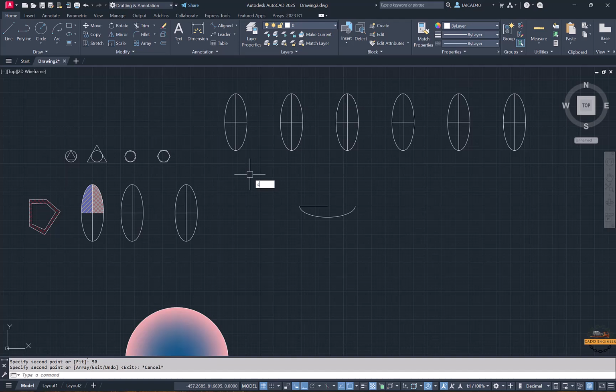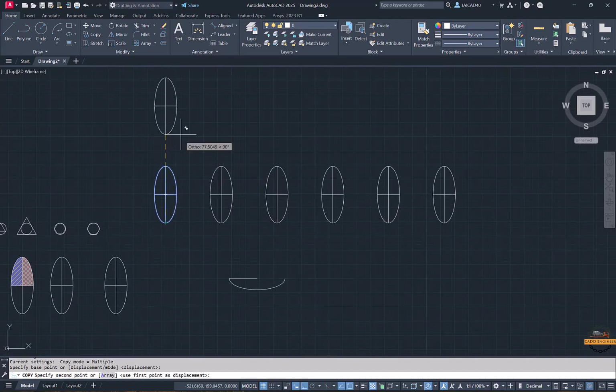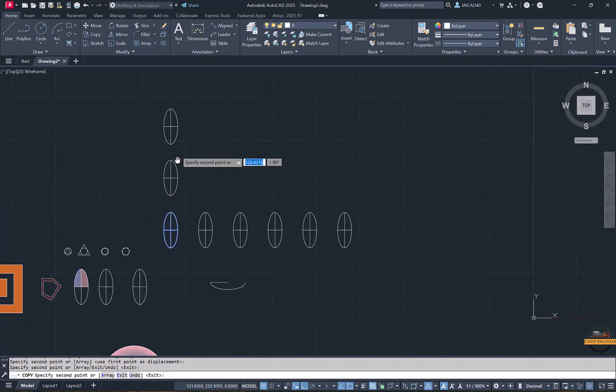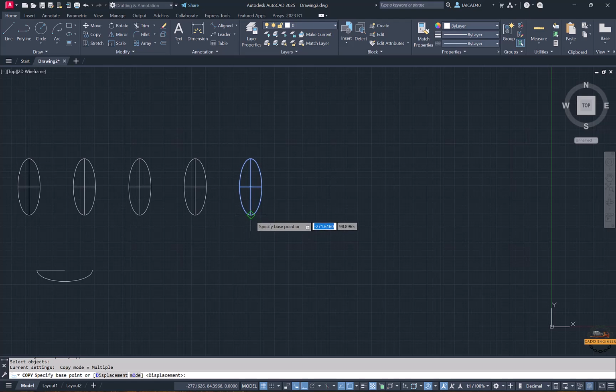Now initially when we take the copy tool, let me take copy and we can pick from any point. Okay. So when we pick copy and we continuously click, it will make continuous copies. But if I want that after I make one copy the command is canceled the second time, we can do one more thing: copy, select the object, enter, and base point, and okay.